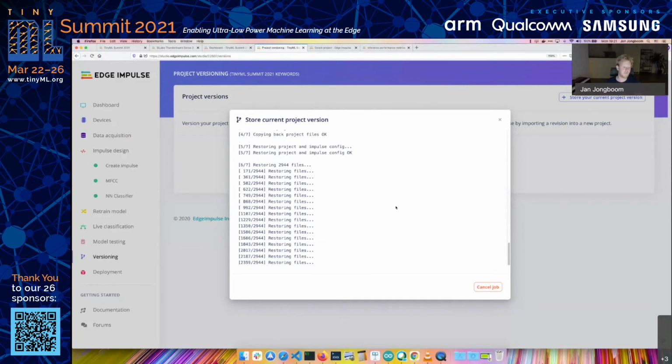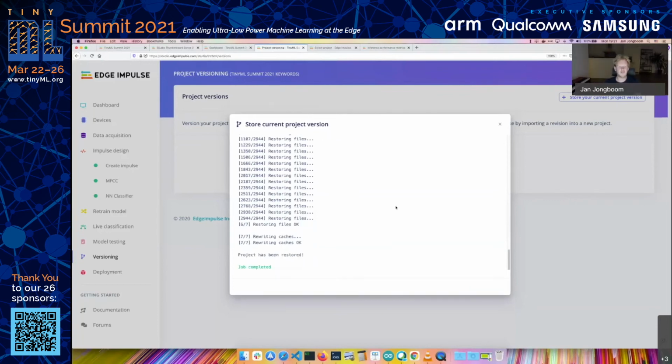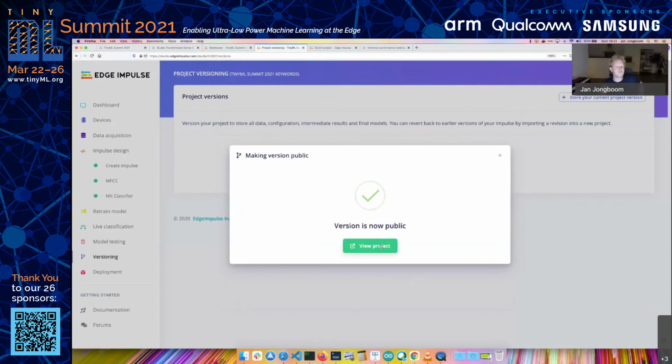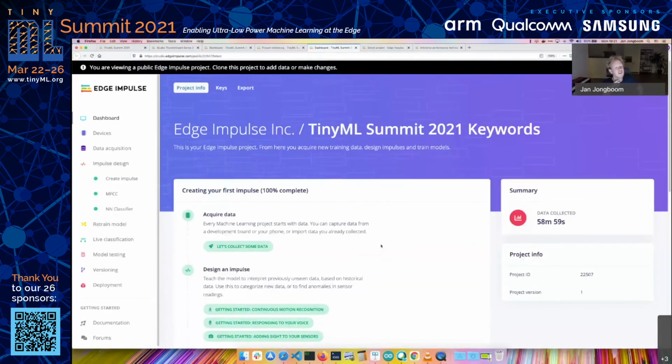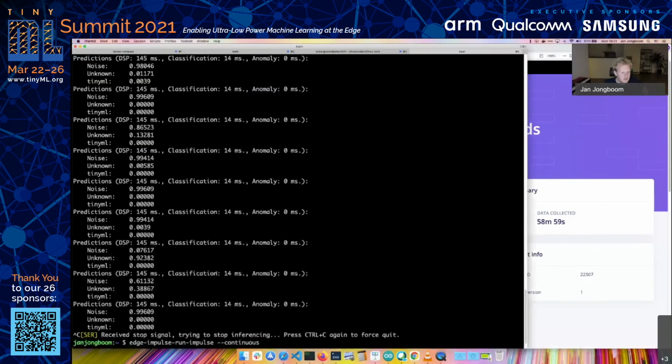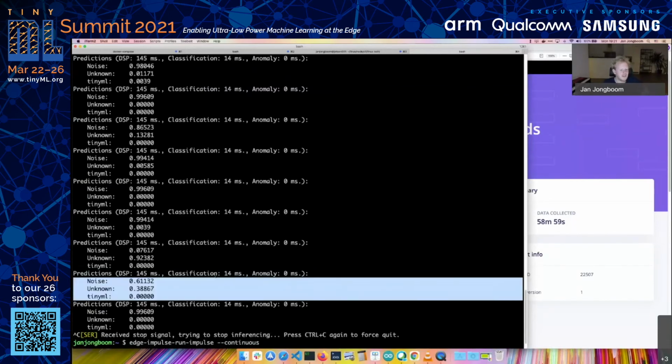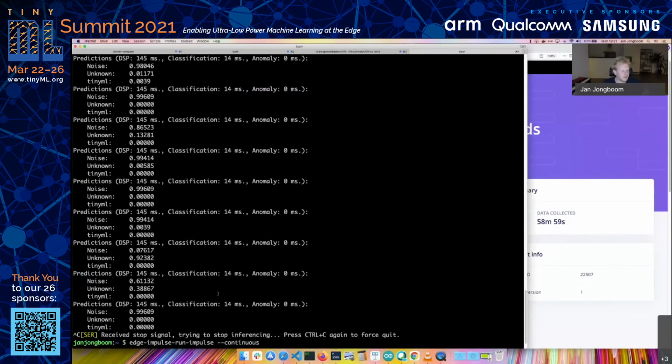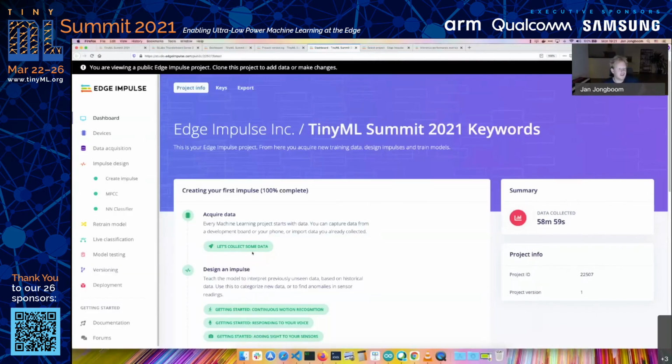So typically what we say is that you can switch to a low power mode when you want to do data collection, because you don't need lots of processing for that. And then you burst to the highest power mode the moment that you want to run inferencing. So for the model here, we spend about 160 milliseconds per inference. We do it 3 or 4 times a second. That's the moment that we want to jump to higher power consumption. Other than that, we can keep in low power consumption and use a DMA interrupt, for example, to get the new data.